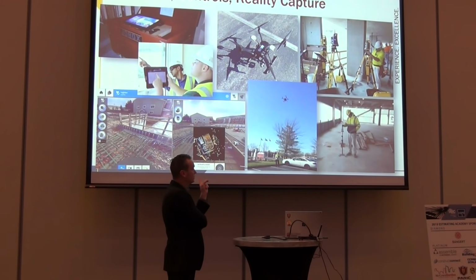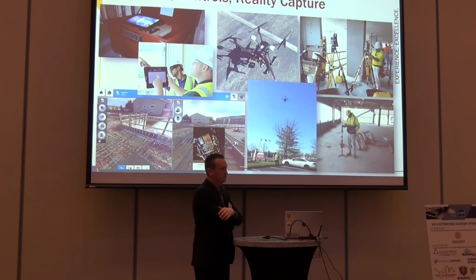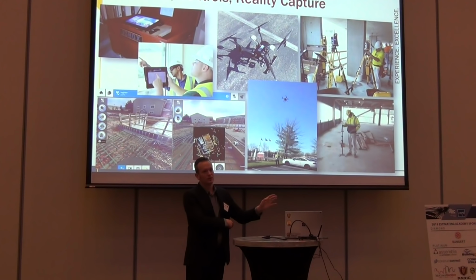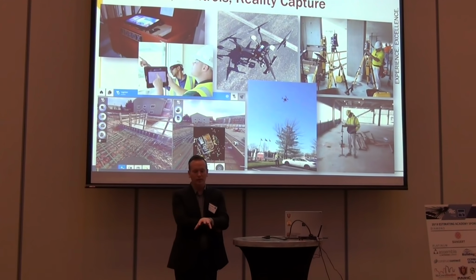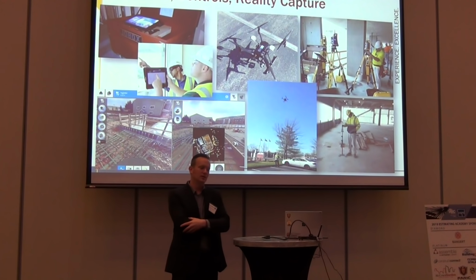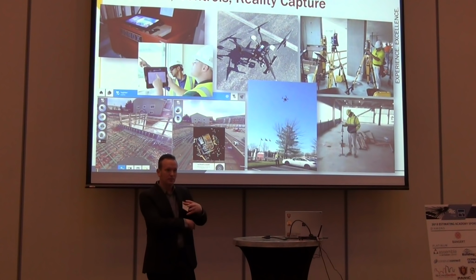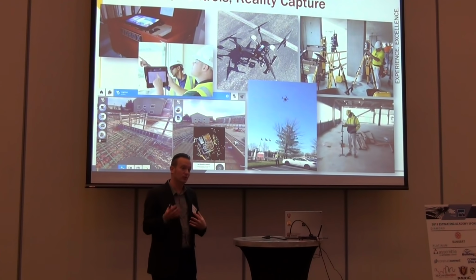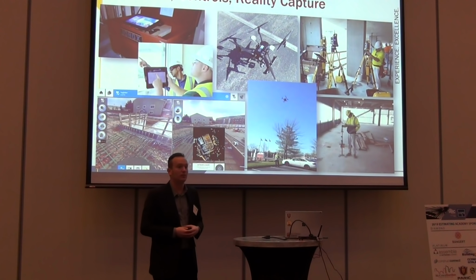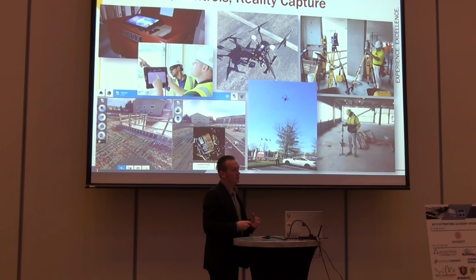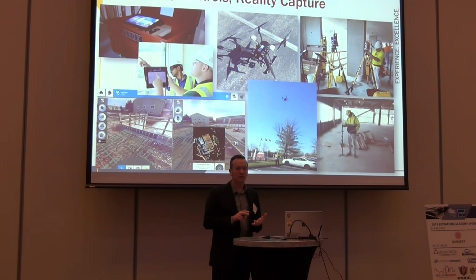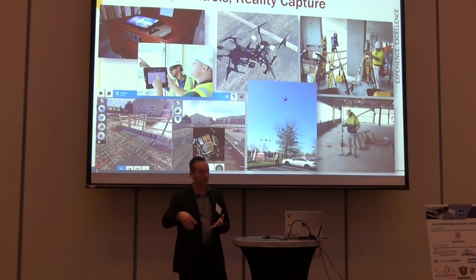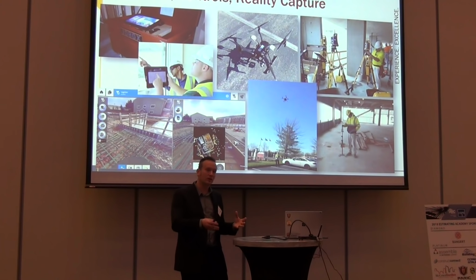So what we do is we'll go out to a project before we've ever won the job, before there's even a contract in the peripheral vision. And we'll go survey the job site on our own. We own control on all of our jobs, because we want to know where that project is in the real world so we understand the context of that project. Then we'll laser scan it if it's an interior piece or areas of the building that you can't see very well. And if I'm an estimator, that's more information, more photos, more pictures of the back end of an operating facility. Drones give us all kinds of insight. They allow us to understand topography, the rooftops of buildings that we can't easily get to, how we're going to traverse a job site that's maybe wooded or where we may have to cut crane paths, things like that.